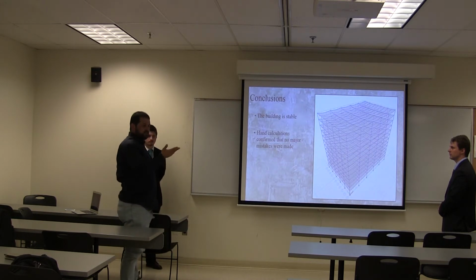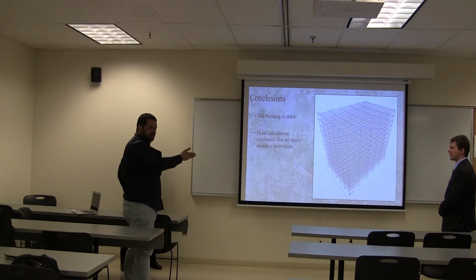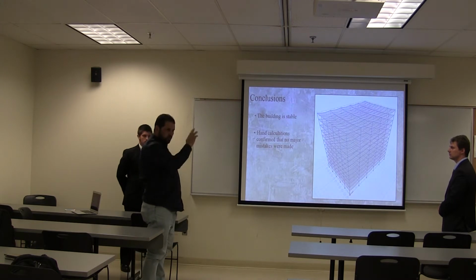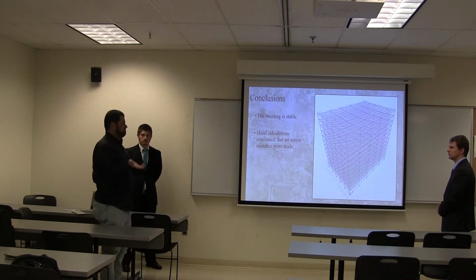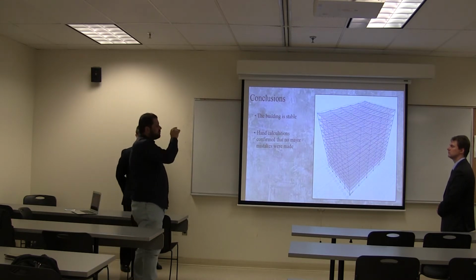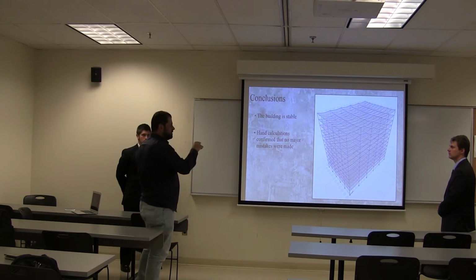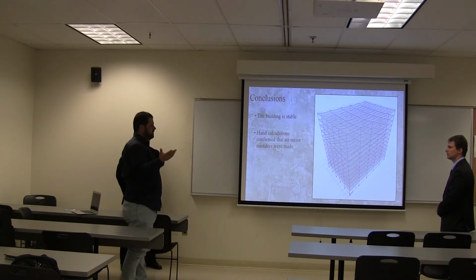20. So the moment for the live load case will be wL squared over 8. So 1 times 20 squared over 8, so 400 over 8, which is 50 kip-foot. If your moment for the live load case shows 50 kip-foot, that's a verification.